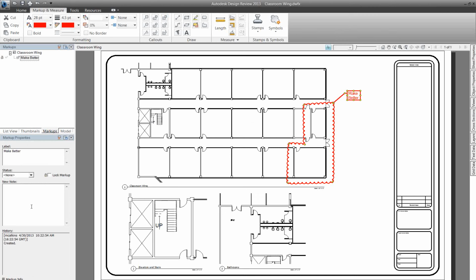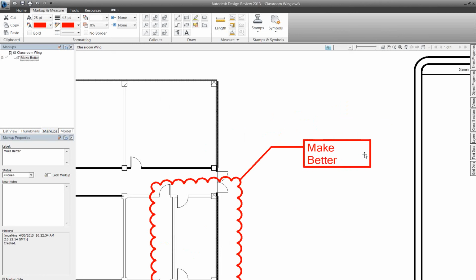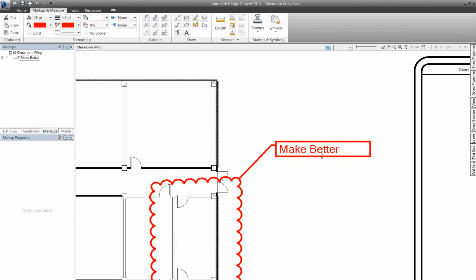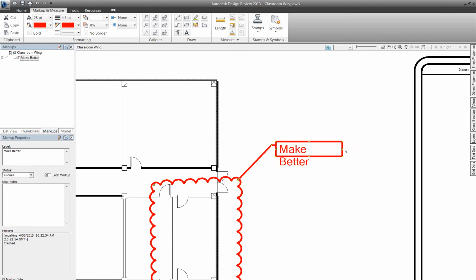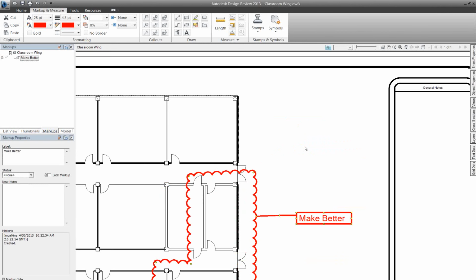Creates a little polycloud, and we see over here, while it's still selected, I can actually view the properties over on the left. Now what's nice about this versus other solutions for marking up electronic printing is that these are editable objects. Do a little zooming. I should note too, you can also zoom and pan just like you can in AutoCAD. So we can actually come in here and adjust the sizes of things to format things exactly as we'd like to see them. And we can actually relocate that if maybe you need to make a change. You see it basically behaves like an intelligent entity there.